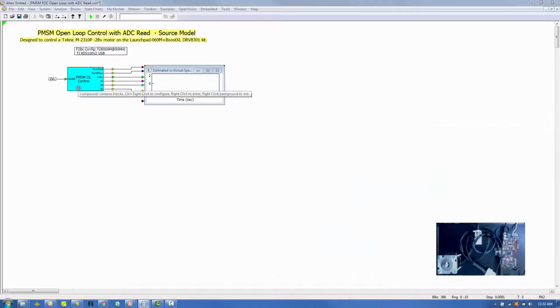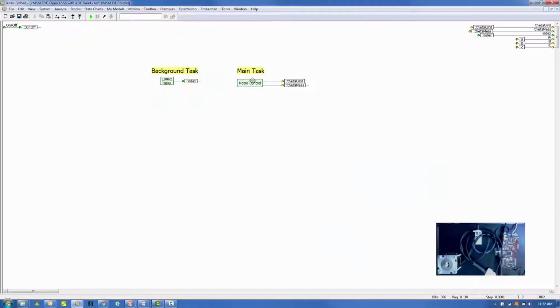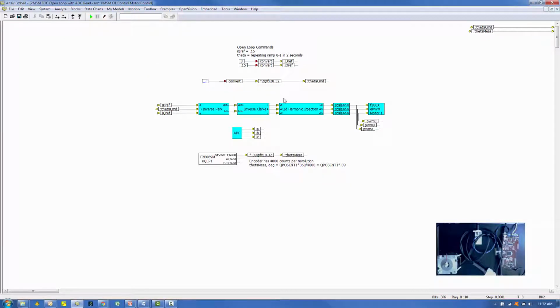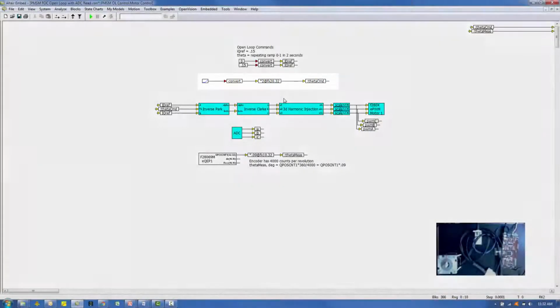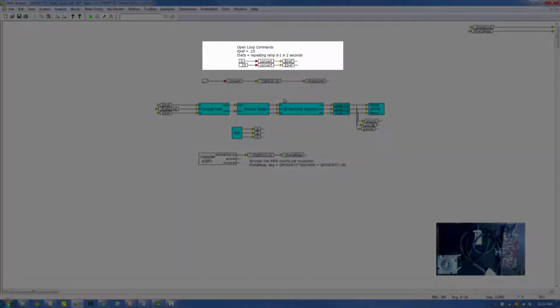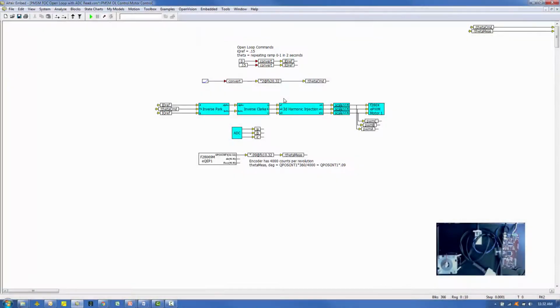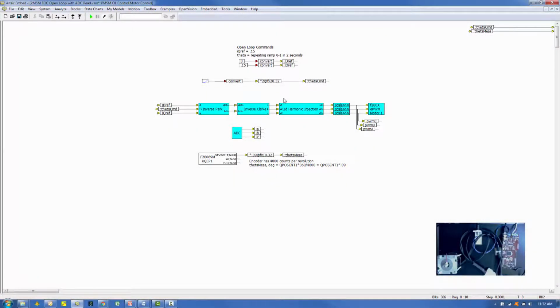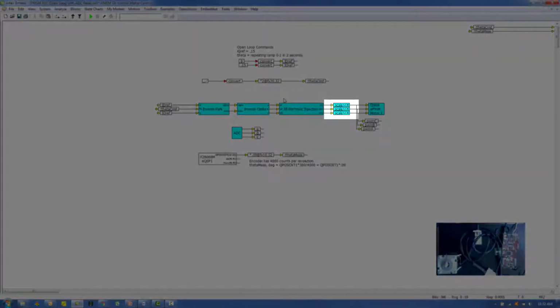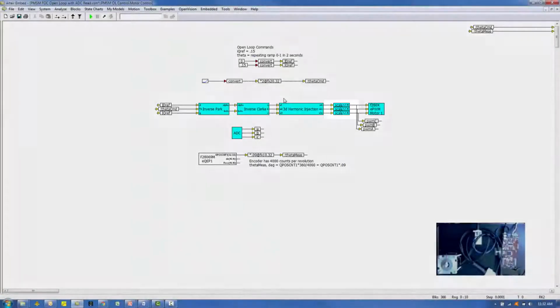Diving into the motor control block of the source model, there are three PWM signals being produced in open loop. The motor angle, theta command, is set to a ramp signal. The flux command, ID ref, is set to 0, and the torque command, IQ ref, is set to 0.15 amps. The open loop control produces three PWM signals, labeled PWM-A, PWM-B, and PWM-C. These signals have been converted to 1.16 scaled integer format in the blocks entitled Scale.